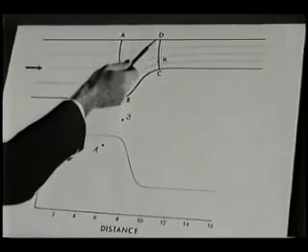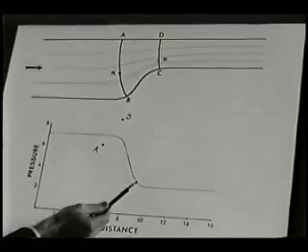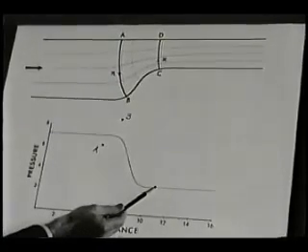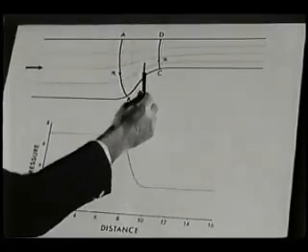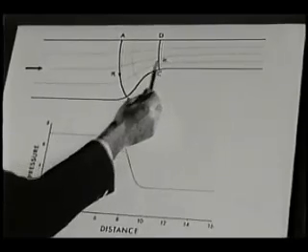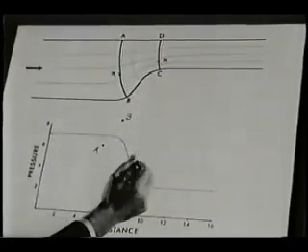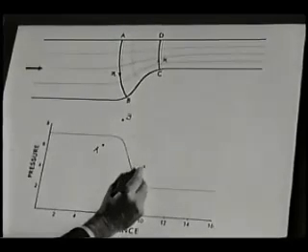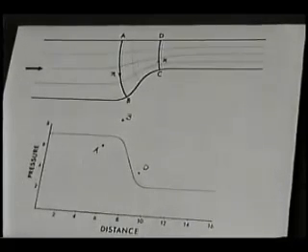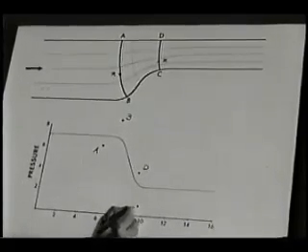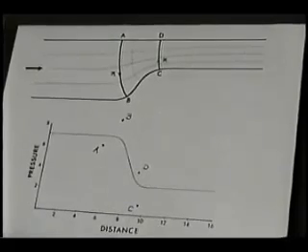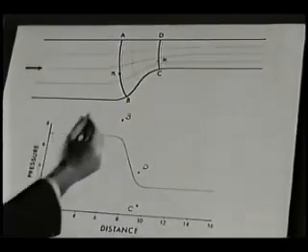So the pressure at D will be greater than the average, while the pressure at C will be less than the average. So the pressure on the curved wall rises to a maximum at B and then falls to a minimum at C. While on the straight wall, it falls continuously from A to D.